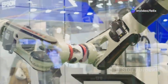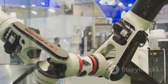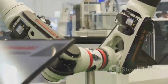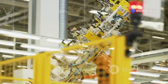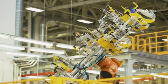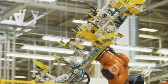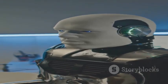Understanding these specs helps you pick the right robot for the job, whether it's in manufacturing, healthcare, or research. Matching specs to the task ensures the robot performs well and reliably. To wrap it up, remember the key specs: payload capacity, degrees of freedom, work envelope, accuracy, speed, power source, and control system. These determine the robot's fit for various tasks and industries.